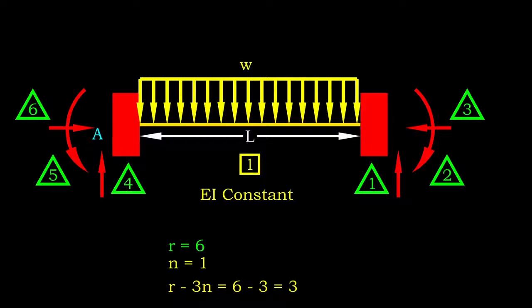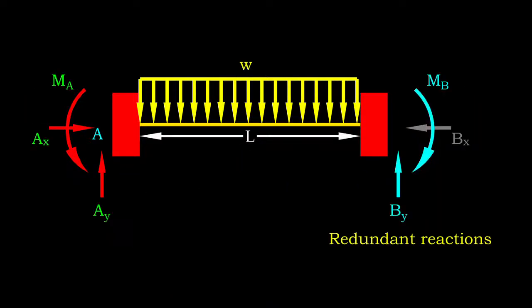For those who don't know, the fixed end moment formula hastens our process in determining reactions and internal forces developed in a statically indeterminate beam. Let's say we have a fixed end beam subjected to a uniformly distributed load W. The degree of indeterminacy is 3.